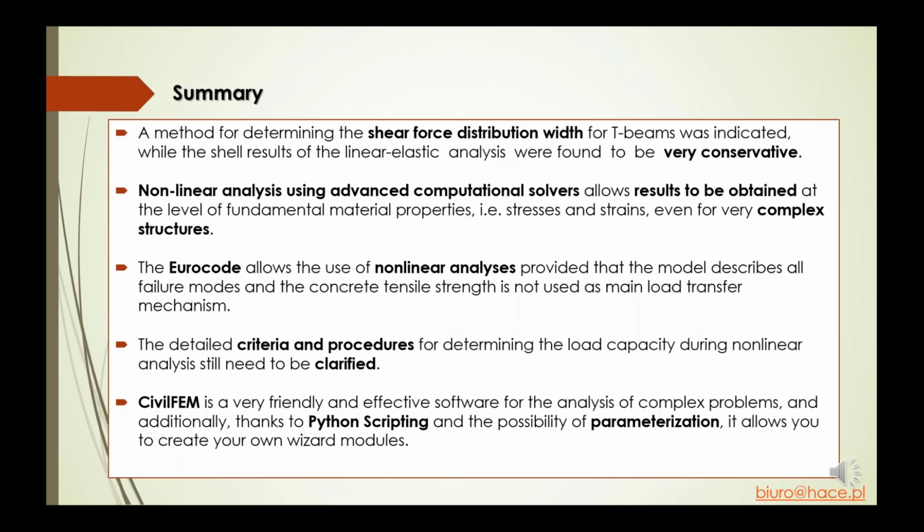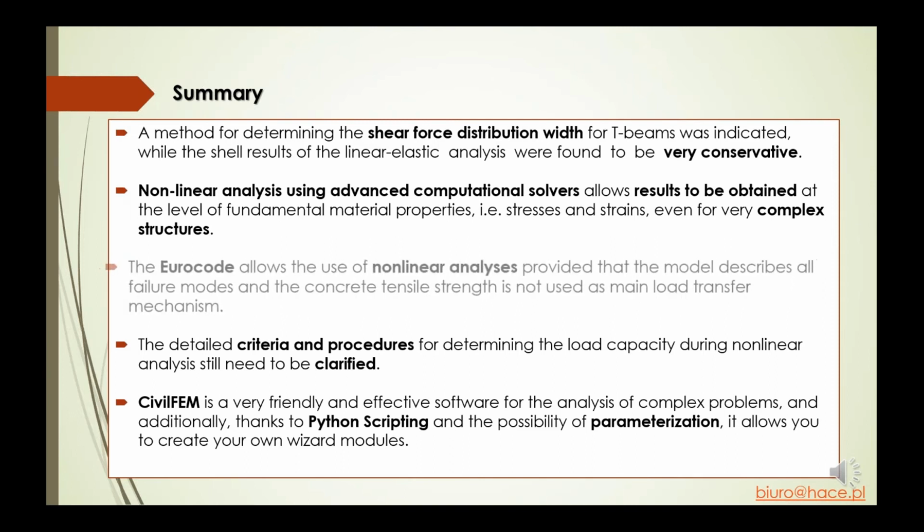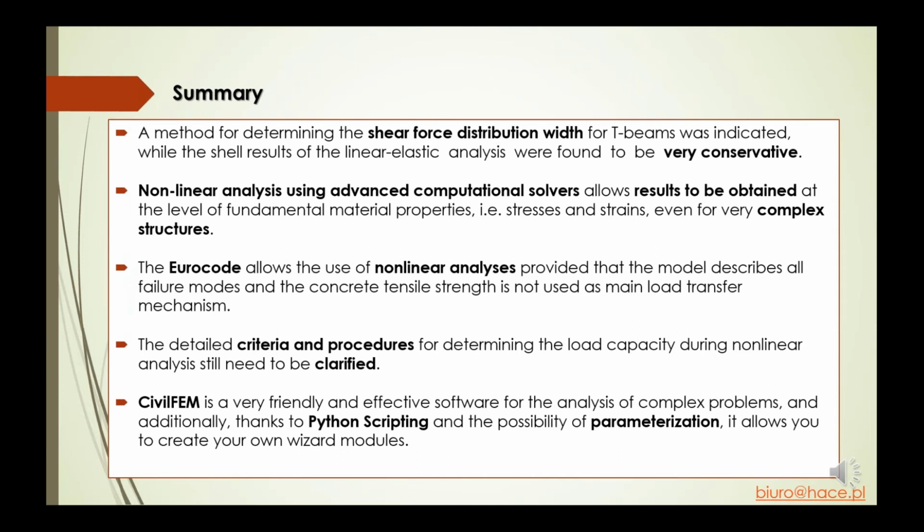Okay. Well, as a summary, here we have two models, a linear elastic and a nonlinear model. We found that the results of the linear analysis were very conservative, so we performed a nonlinear analysis. Eurocode allows the use of nonlinear analysis, describing all the failure modes, and the detailed criteria and procedures for determining the load capacity, in this case 1.5, still need to be clarified. CivilFEM is a powerful, friendly and effective software, and with the help of Python scripting and the possibility of parameterization, you can create your own wizard.